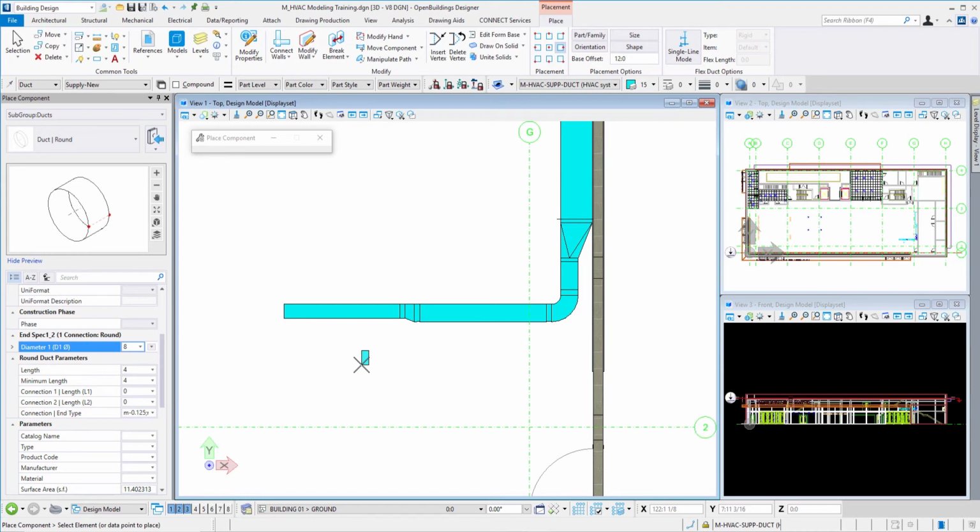So by utilizing that placement option for the justification of our ductwork, we can avoid obstacles in our other disciplines, or if we need to stay flush with a structural wall, for example, we can achieve that and use that justification placement setting to our advantage.